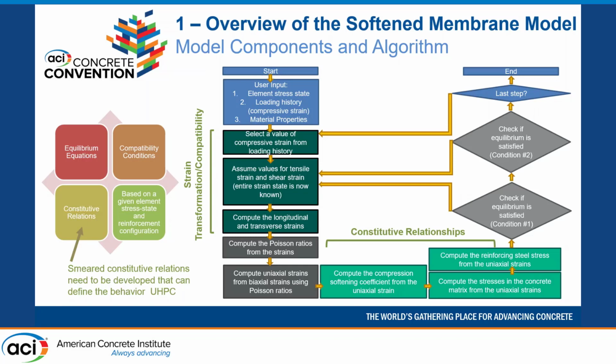And so the model equilibrium equations and compatibility conditions don't vary based on the material that you're dealing with, but what's very important to take into account for UHPC is the constitutive relationships in the model, which need to be further developed and investigated for UHPC, given that it's a very new material.